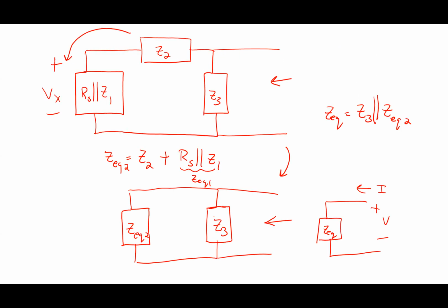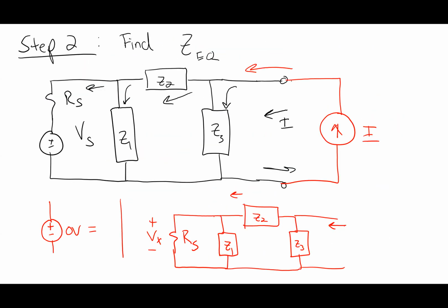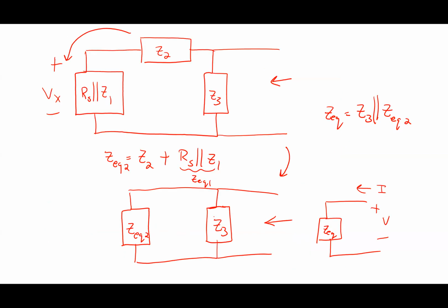Important thing, and the main thing that most people get wrong, is they start combining in the wrong direction, right? They don't start by the impedance looking into the terminals. They start back there, and they start saying, well, RS is in series with whatever's down here. You're immediately wrong right off the bat. Now you will need that though, if I want to do the other step, which is to figure out the open circuit voltage. All right, so back to the original network here.